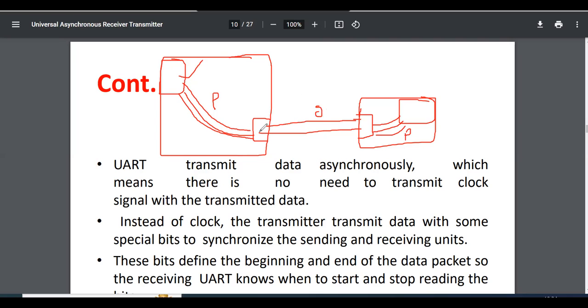So what it does, your master side gets parallel data and converts it to serial. That serial data is sent to the next port. From this port the data has to be converted to parallel again to send to the processor. Did you understand? For this communication, only at this point we use the UART protocol for serial transmission. But wherever it is transmitting in parallel, we will use the AXI or AHB bus protocols. Here we will use AXI interfaces. Okay, did you understand, everyone?